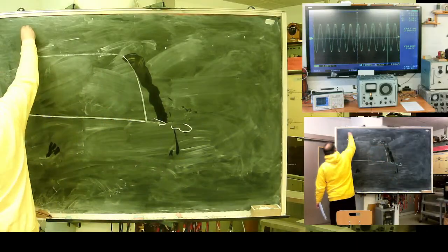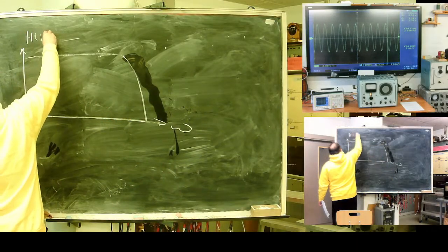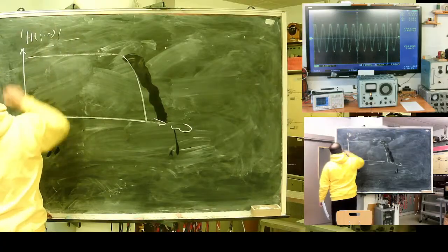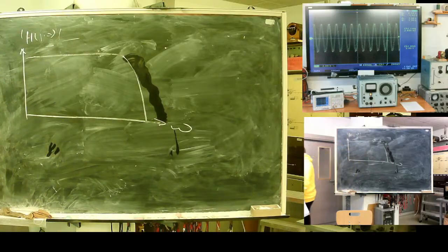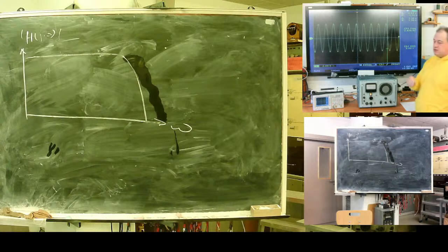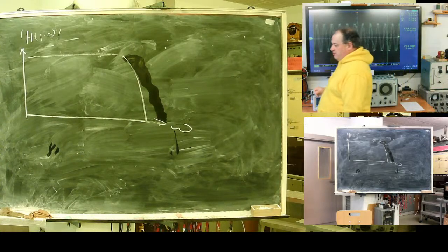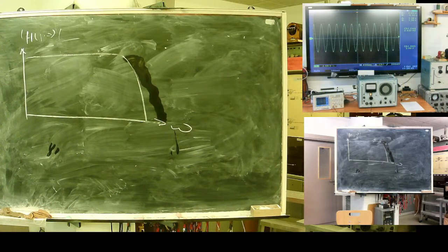Frequency, magnitude of transfer function. But there is one problem with Butterworth filter that works very fine when you deal with stationary repeats. The problem is the transient characteristic of Butterworth filter.